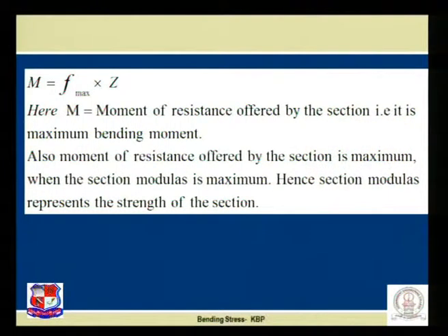Now M is equal to F max into Z. Here M is the moment of resistance offered by the section, that is, the maximum bending moment. Also, the moment of resistance offered by the section is maximum when the section modulus is maximum. Hence, section modulus represents the strength of the section.